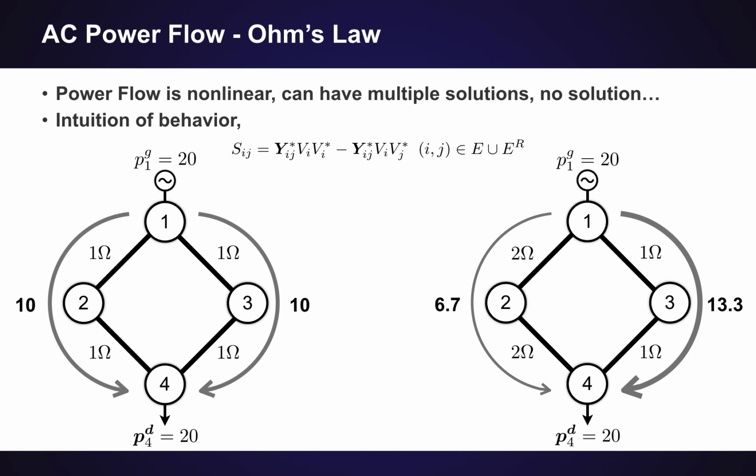And for a certain set of power injections or power consumptions, there might be no set of voltages that give us these power injections. Usually, if we do have voltages specified, we should be able to find power injections that correspond to them, but those power injections might not be the ones that we want. Right. Yeah.